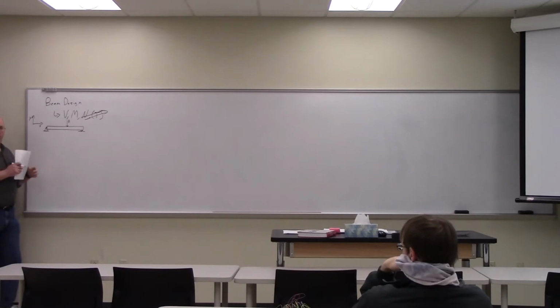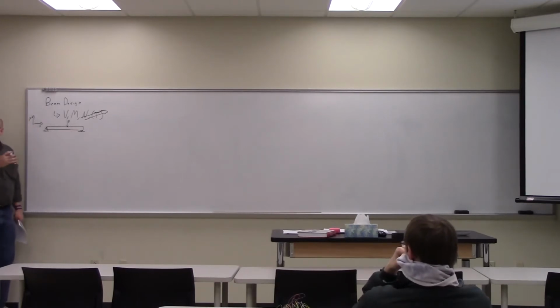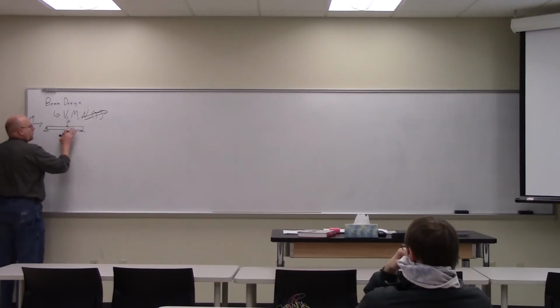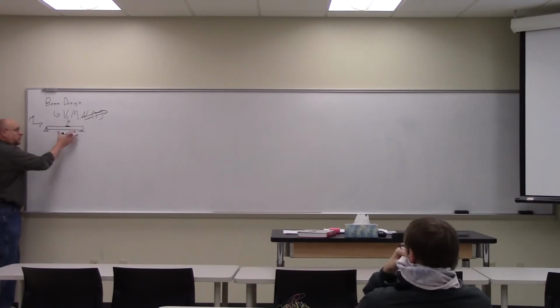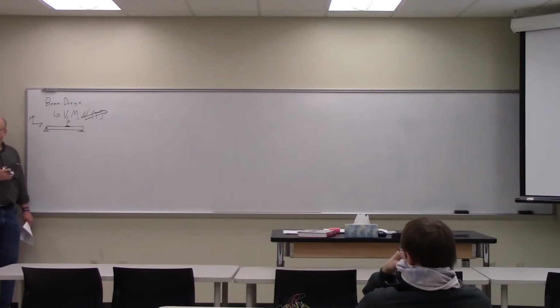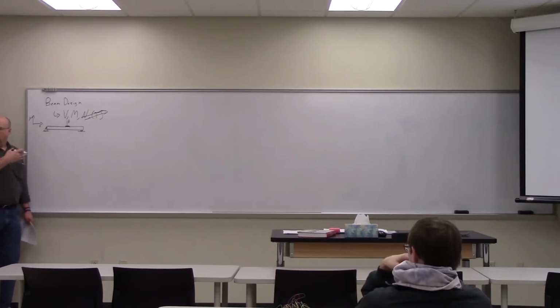You understand what I'm saying? So sigma Y may be great here, but because this point is supported by a wide range of material around it, that sigma Y dissipates as it goes back into the beam. Okay? Furthermore, we will often, in reality, put a bearing plate at the point where the load is applied. The purpose of which is to specifically distribute that normal load, that lateral load, so that instead of being applied at a point, it is applied over some distributed distance.